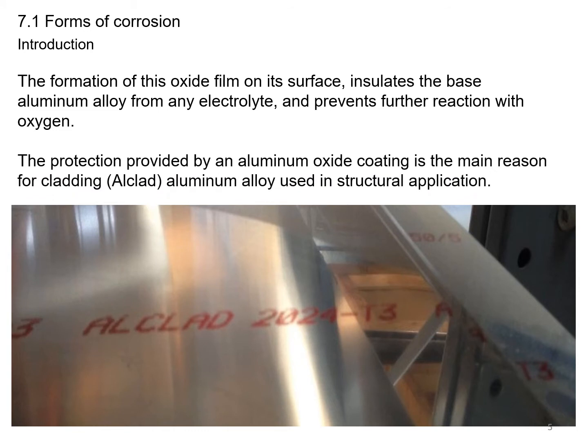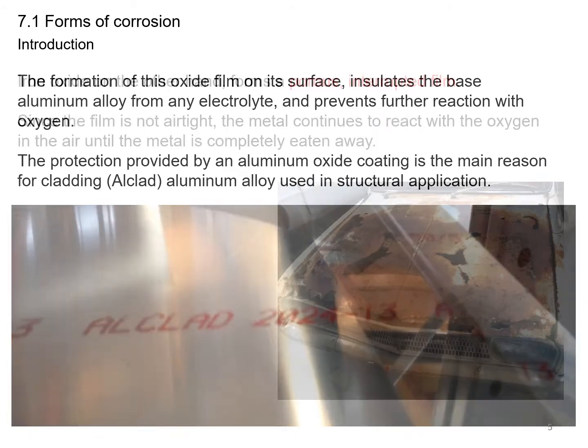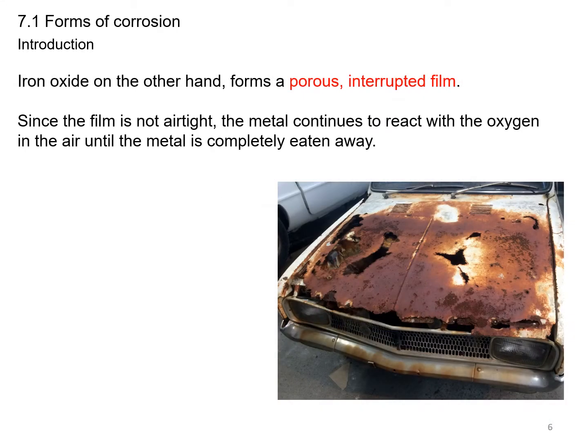Protection provided by the aluminum oxide coating is the main reason for cladding, or what we call Alclad. So Alclad aluminum alloy is used in structural applications. Iron oxide, on the other hand, forms a porous, interrupted film. Since the film is not airtight, the metal continues to react with oxygen in the air until the metal is completely eaten away. You can see from that picture that this car's hood is slowly returning to its native state of oxide.